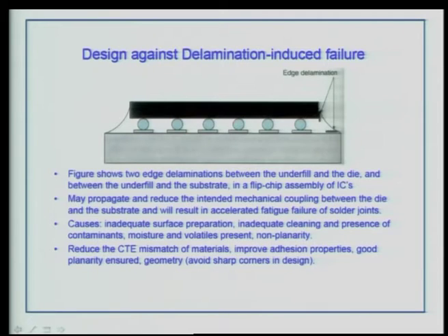Then again you have to design against delamination induced failure. This is very typical of flip chip connections where an underfill is used, and you can also have cracks in the underfill close to the edge of the chip or close to the edge of the PCB.